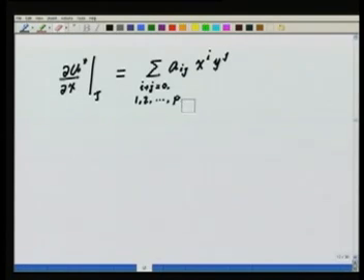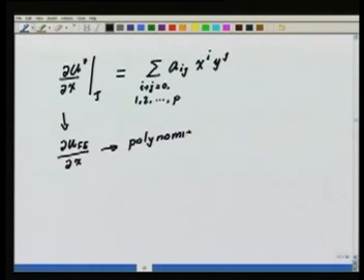P + 1 or p will do fine, because the finite element solution ∂u_FE/∂x will essentially be a polynomial of order p minus 1 in the element. So for this we take one order higher, we could take two orders higher also, and we will take it as a polynomial of order p. This is what I would like to obtain out of my finite element data.